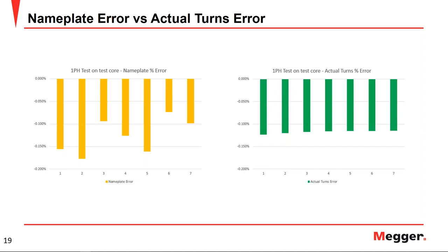There are certain scenarios, for example, a DTC being a long period in service, where sometimes we just don't change the position. We leave it at whatever it is, the service position. But when you do have to run the whole run of positions in the tap changer, you do as many tests as positions you have in the tap changer.